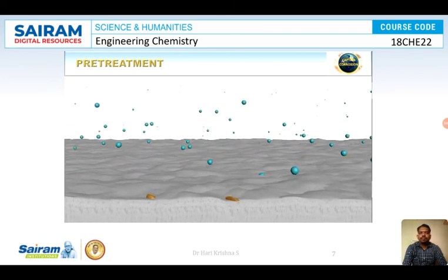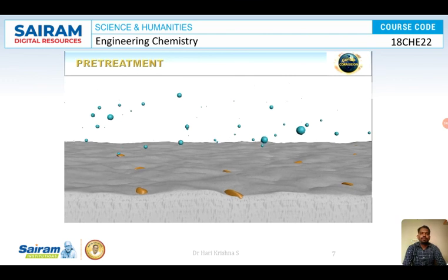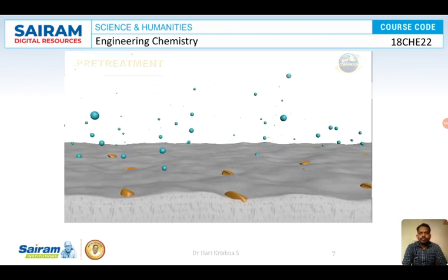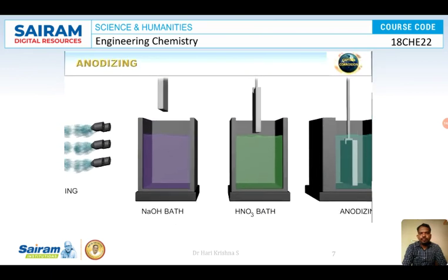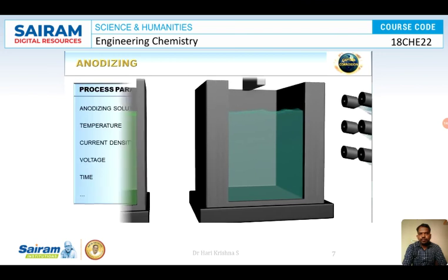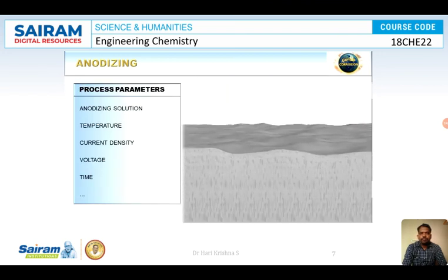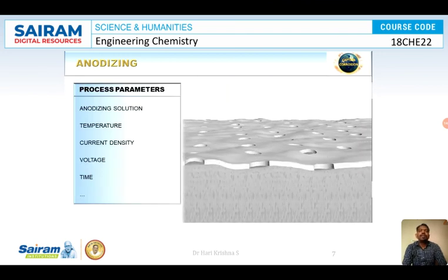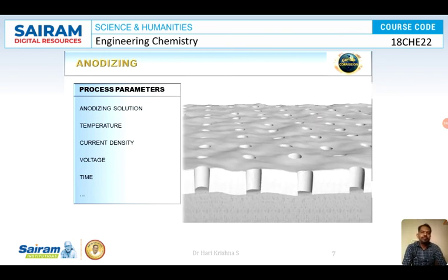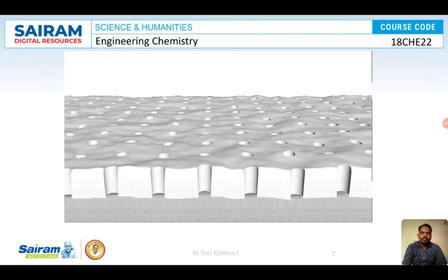The chemical treatment stages are sometimes not necessary if the mechanical treatment is already sufficient. Anyhow, the freshly treated metal is then anodized, where the anodizing parameters, such as temperature, are selected based on final application. There will be small pores, you can see there, right? This pore should be blocked.